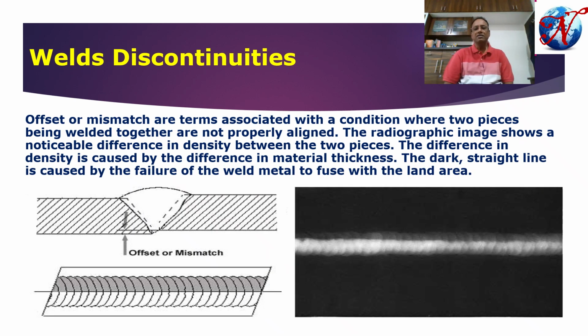If a welded joint has a mismatch, in the sense there is a thickness variation, or there is an offset or angular displacement, the appearance of the weld will be like that. But a mismatch up to a certain degree is acceptable, as long as other welding defects like lack of penetration, too much undercut, and lack of fusion are not present.